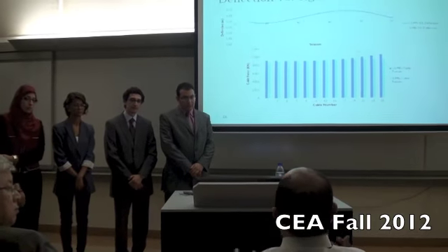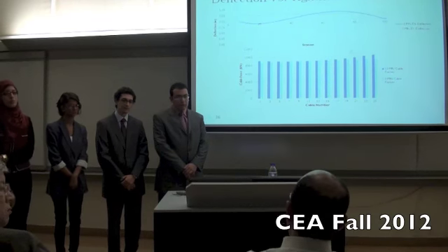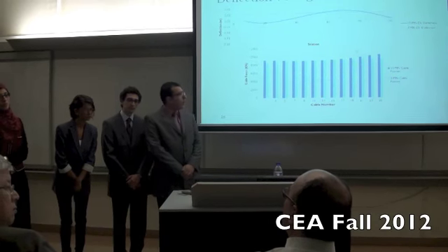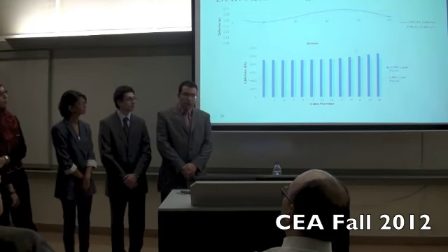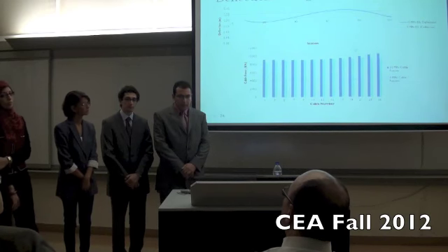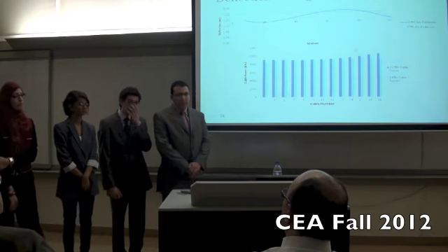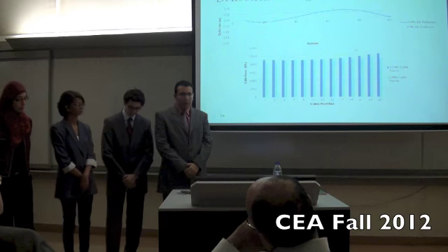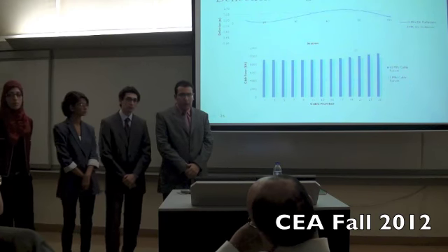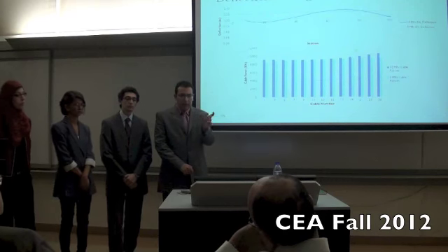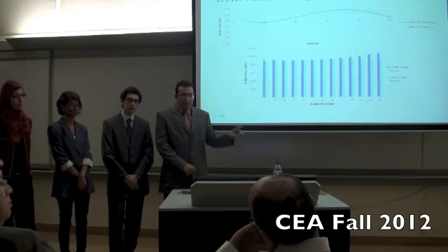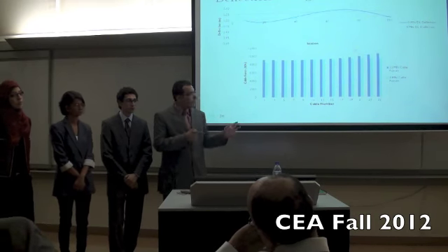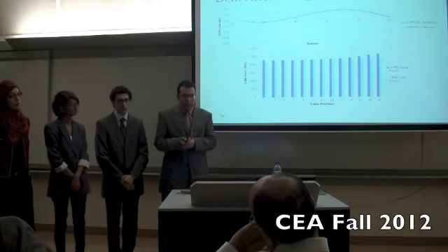I start with a question. You have a numerical model, right? How do you know that those results are correct? We compare them to other cable stayed bridges. We compare the areas of the cables. The depth is actually to determine the 3-meter depth of the box section. We did a literature review over around 7 bridges, and we calculated the span to depth ratio of all of these cable stayed bridges, and we accounted for either they have 1 pylon or 2 pylons, and we came with these numbers, and they were close to the ones used.